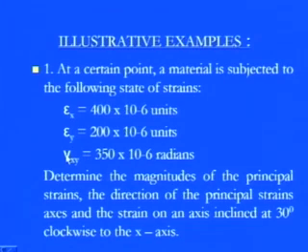If we can put the x dash, y dash, make the diameter, draw the circle, get the value of the center, get the value of this epsilon 1 and epsilon 2, and these are the principal strains, and then measure the 2 theta, through which we can get this angle where it is now. And then you see, we can get it by simply rotating 30 degrees towards the clockwise direction of the x axis. So you see all these things are pretty straightforward.